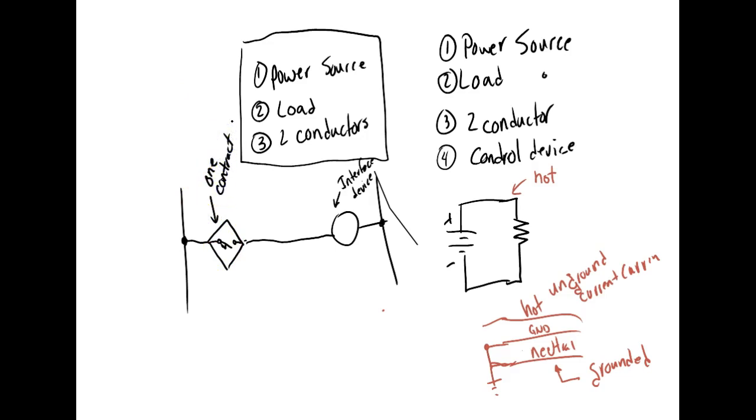And if you have one that has more than one contact, that's the exception, not the norm. Now, some solid state sensors can power up through the circuit. So if this is 1K and this right here is 200K, there's current flow through the solid state sensor. It's just so small that we can't measure it. So the inductive sensor that we're using powers up through this load right here.